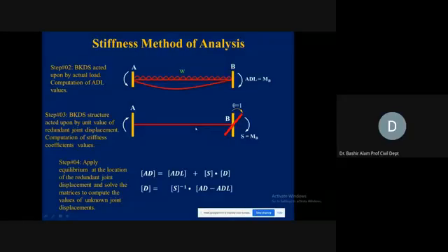But right now you should know the concept. It is exactly the same as what we did in the flexibility method. We released the redundant action here, and because of that we ran into the compatibility problem because we had the displacement here. Now, instead of the displacement, we have an action problem here. It is not matching the initial condition. In that procedure, we applied the unit load multiplied by whatever load is required to bring it back to its position.